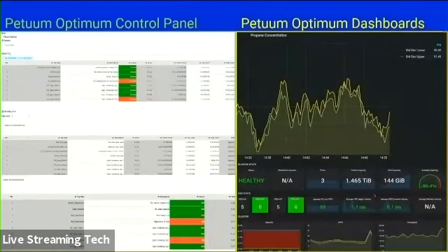And then this is what the operator sees. For every variable, you have one actual measure, and then you are always looking at the forecast of the specific variable. You have also the dashboard on the left, where you are looking at the manipulated variables, control variables, disturbance variables, and you can select which ones you want to activate or deactivate. Let's say that I am an operator and say, I don't want the AI to take control of this variable. I will turn it off and I will control it myself. That's possible, right? So all of those combinations.